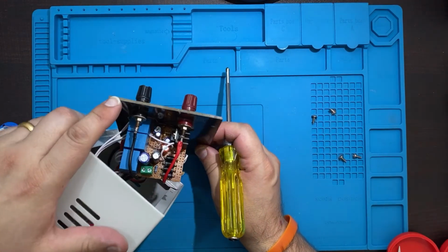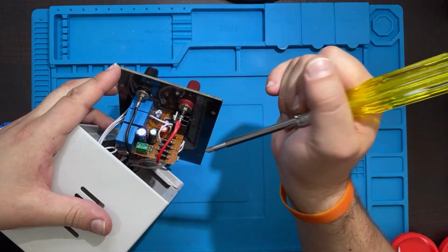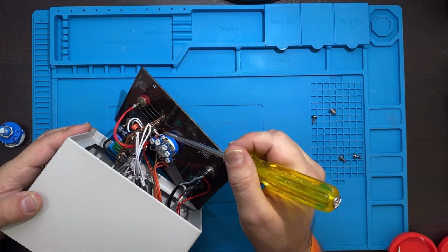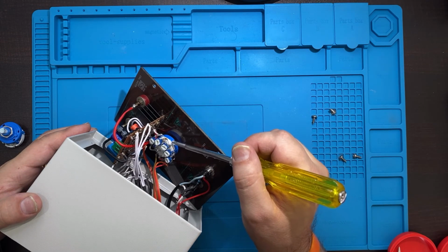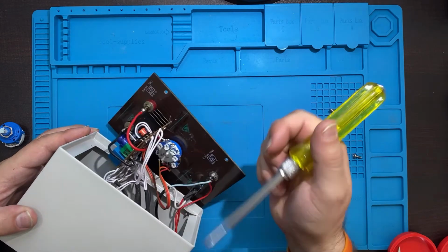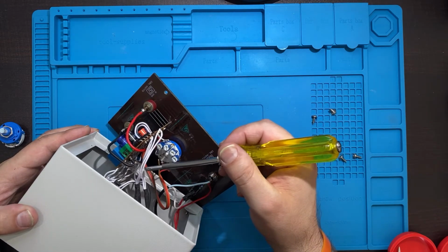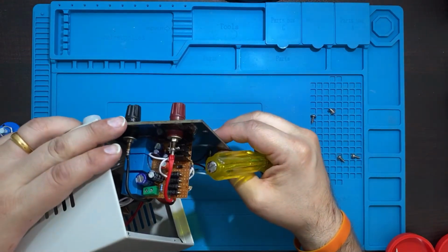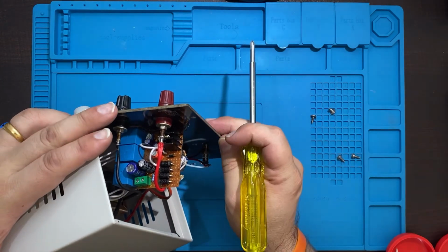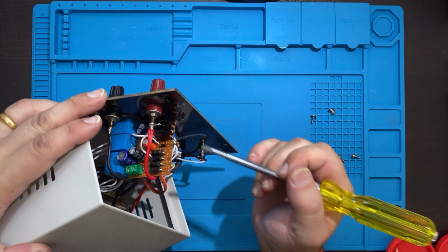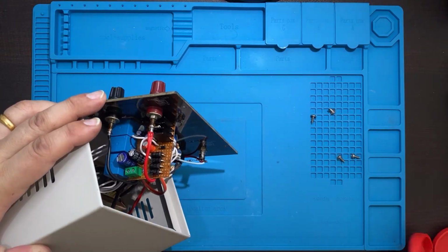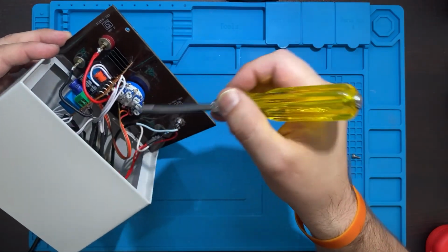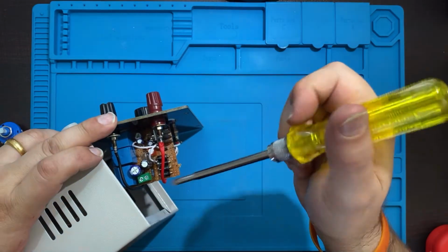Now, what did I do here? So here are the relays, and I had to put this board here on the panel to keep the wires that go through the rotary switch as short as possible, because the induction getting into the feedback circuit of the regulator was a bit weird. It was picking up some of the hum, and it was coming out on the output.